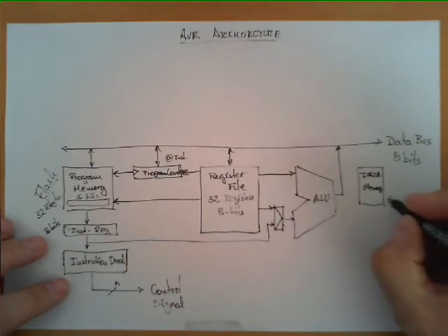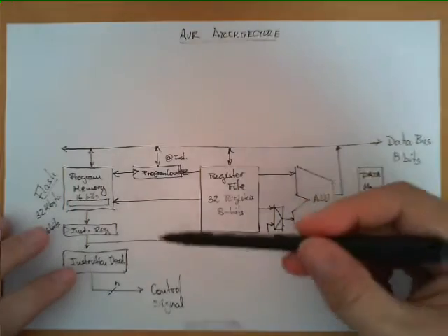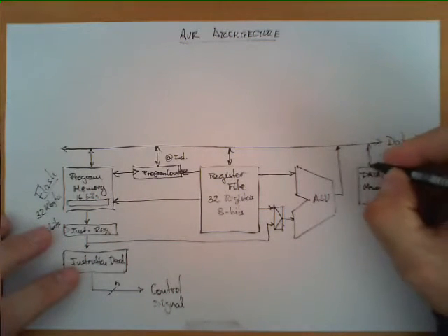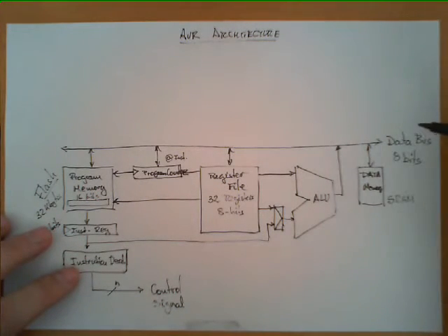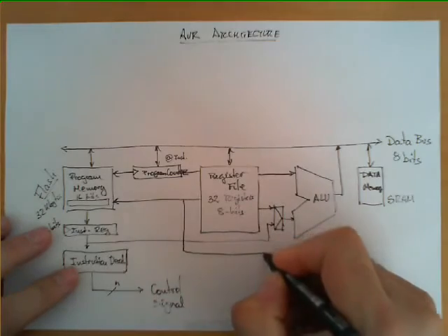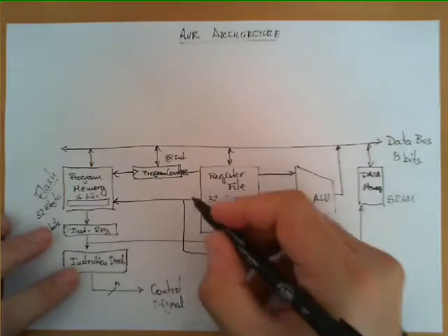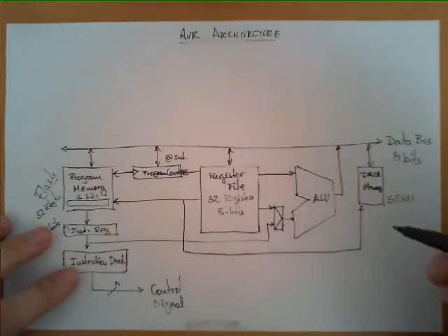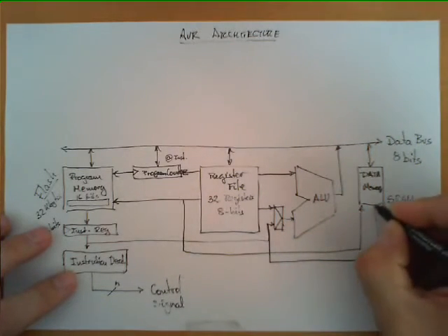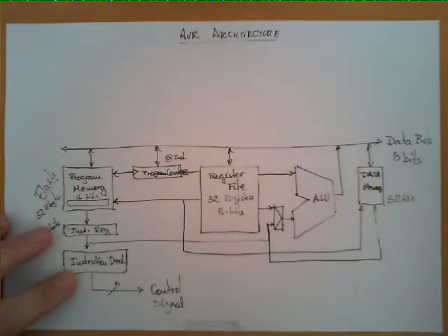This data memory, which by the way is of type SRAM, is implemented so that the program manipulates certain data that is stored in this chip over here. It also has a connection to the data bus, as everything else, and the two connections that this block receives are, first, one from the register file. In other words, from the register file we can obtain a memory address or data that is going to be written in memory, and the other, which is also very important, is an extension of this immediate line coming from the instruction register that goes all the way to the data memory.